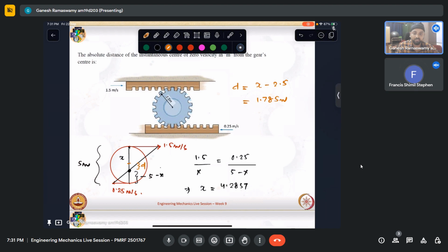That is what we have found, that it isn't. It is at a distance 5 minus x, where x is not 5. So it is a non-zero quantity. So it is not rolling about this point. Yeah, you can say that. Since this has some velocity, by virtue of this body being rigid, it can have only one omega, in which case it would have to be evaluated by these two velocities.